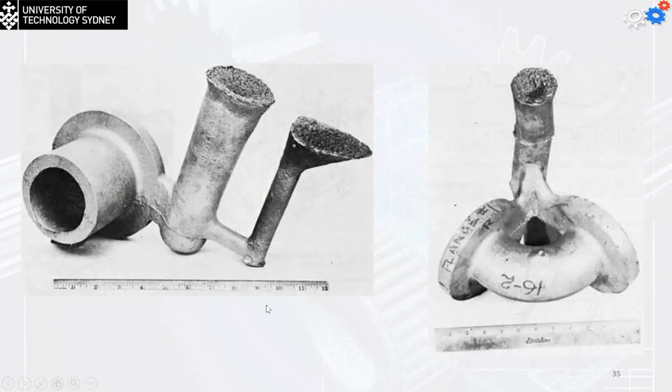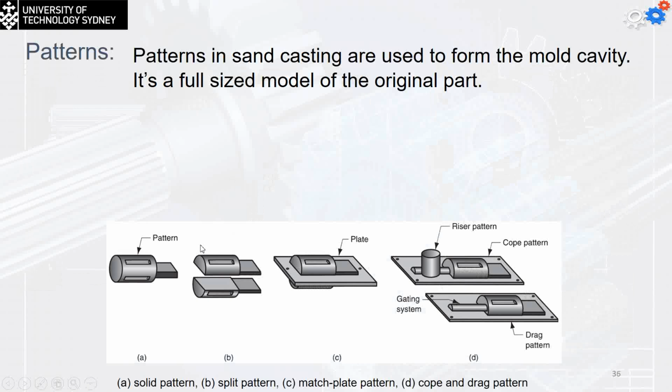So this is an example of the sand casting process for different shapes. Now this one, the one to the left, shows you obviously the pouring cup, the upright flask, and we have the riser and the finished part through the runner parts.